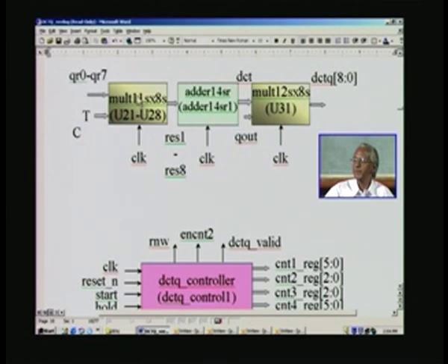And after this, what we have multiplied, 8 results are there here, result 1 through 8, and all of this we have to add, and we need one more adder, which is 14 bit with registered output. This is what I gave as an assignment earlier, and I hope that you have done it, so I am not going to show it. You were also given an assignment for this multiplier as well as this multiplier, and this multiplier is to create DCTQ out of DCT, and this is nothing other than adding all this row into column multiplied here in order to get the DCT here.